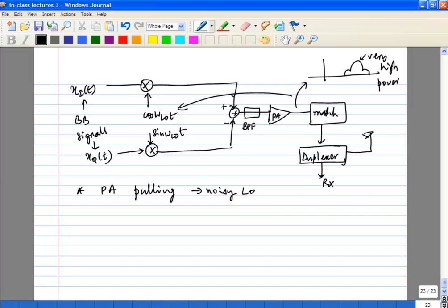Typically the main path you want to use is, if you have a voltage controlled oscillator, a DC voltage. You would have studied this in the PLLs course, in the analog ICs course. So you have a DC voltage produced by some mixed signal system, and the DC voltage is what controls the oscillation frequency of the VCO. If you have a second path, that's usually called the injection lock path. If there is some signal coupling in through a different path and the output frequency of the VCO does depend on this, it is called injection locking.